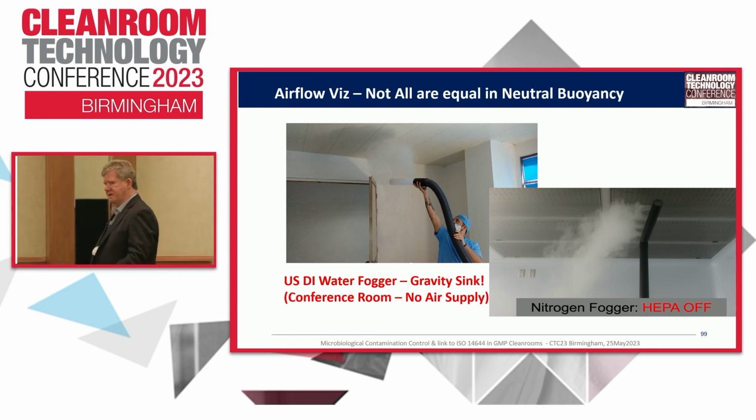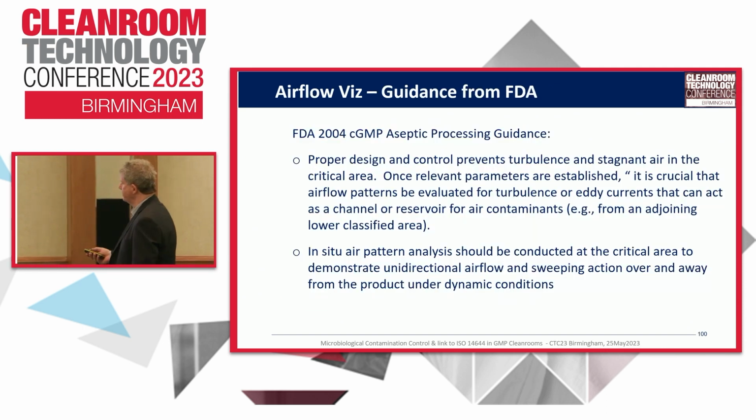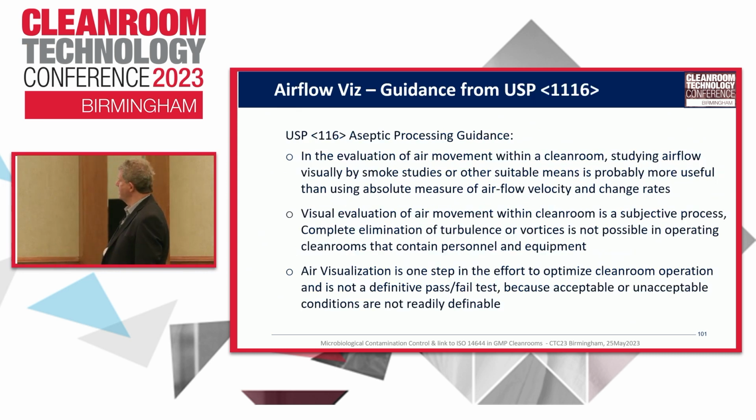So CFD is really important, but you need to marry CFD, as in computational fluid dynamics, around airflow patterns and studies on that side. Okay, so there's notes from FDA from 2004 around it being crucial that airflow patterns are evaluated for turbulence or eddy currents that act as a channel reservoir for air contaminants. That's out of 2004. You have guidance in USP 1116 on it. Visual movement is subject to process, but it's one step in the effort, back to this holistic view in Annex 1.